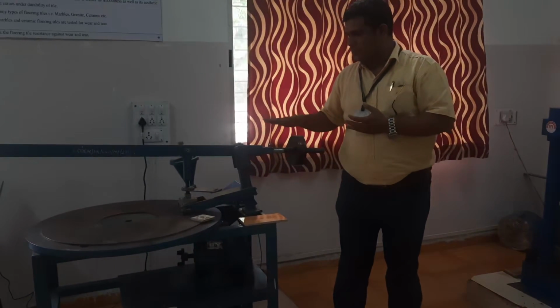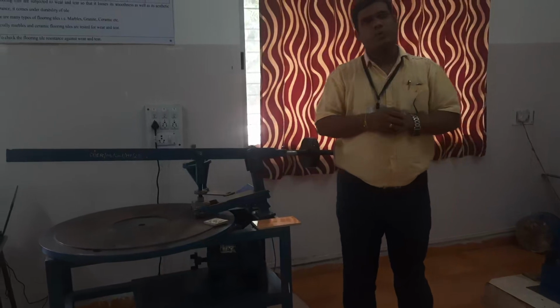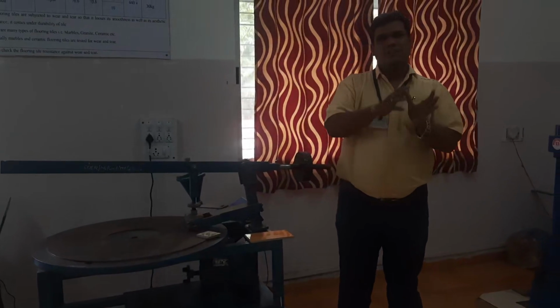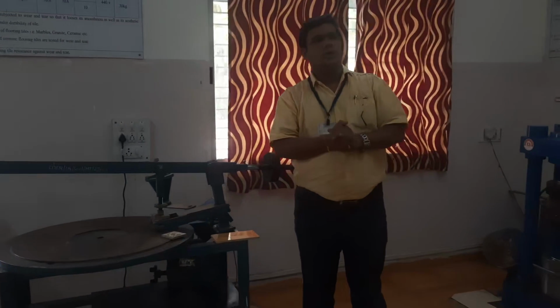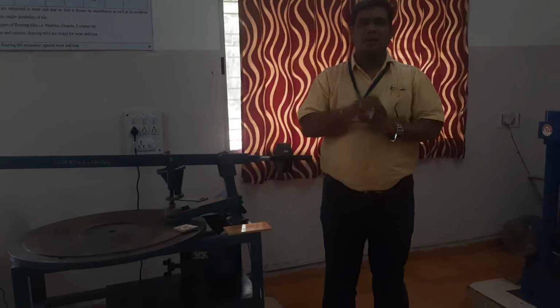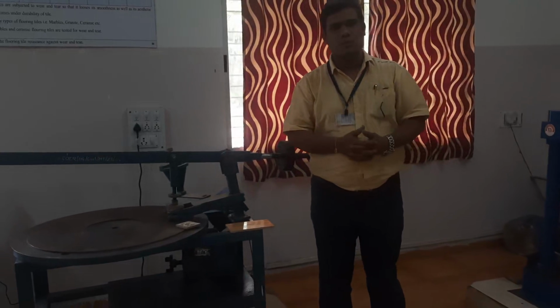This is for your abrasion test. Three specimens should be taken from the lot, and the mean of the abrasion loss in percentage is considered as the abrasion of the tile. Thank you very much.